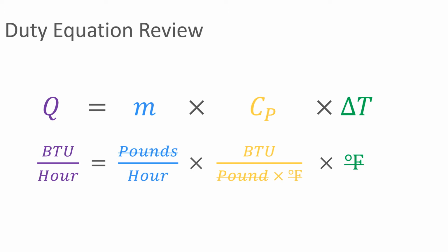The purpose of this slide is dimensional analysis, to illustrate that Q is calculated in BTUs per hour with M Cp delta T. If you do the dimensional analysis, you can see that all the dimensions cross out and we're left with BTUs per hour for Q. What's really important here is that if you really stop to figure out the units that are available for each of the components in this calculation, it helps you understand the basis of the calculation.